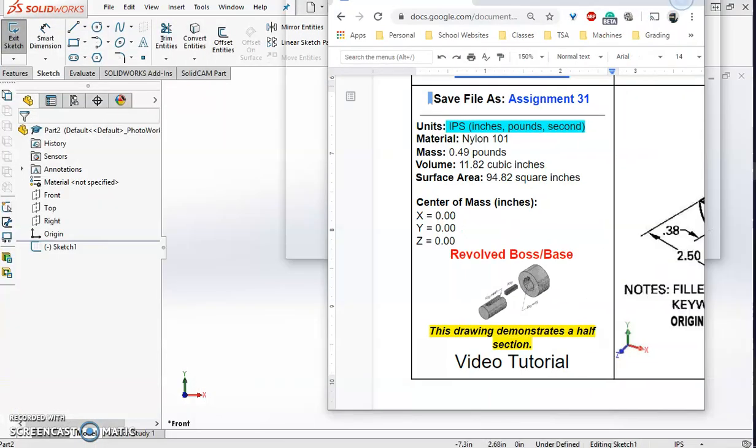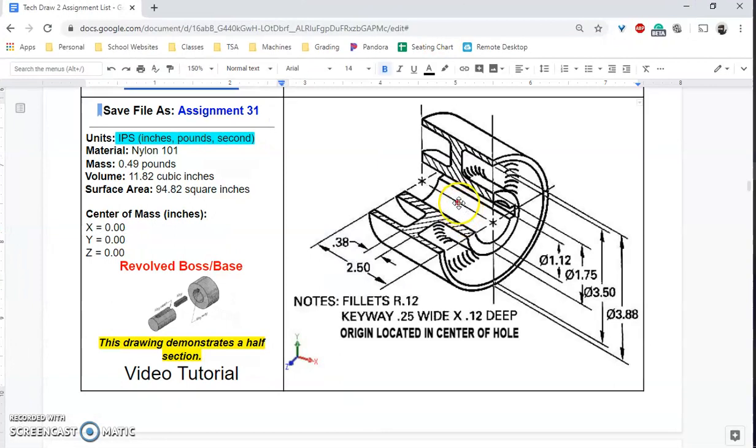Now, if you look at this picture once again, you can see the origin is right in the middle. And in order to have this hole in here, we're not going to have anything connected to it. So this capital I looking shape is going to be moved up from the origin, but it's going to be dead center. The center of this I is going to be right up above this origin. We're going to be using these different diameters and cutting them in half because we're only drawing half of this, so that when this revolves around, you'll get the full diameter. So we're going to be typing in these diameters but dividing by 2 so we can find the radius.